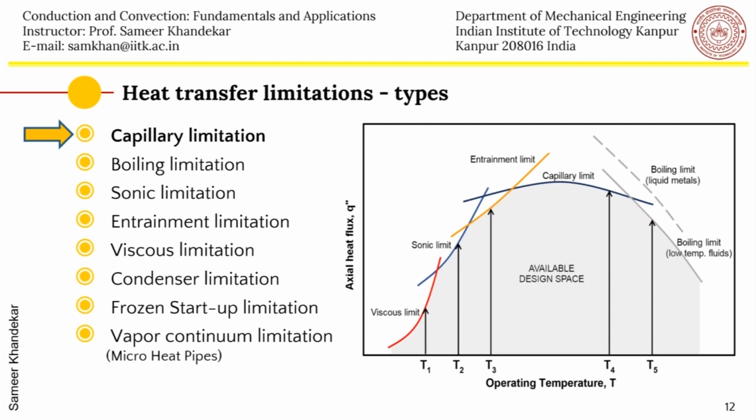As we will see, one can do a theoretical experiment in which you control the operating temperature of the heat pipe, which is usually the adiabatic temperature, by controlling the condenser cooling water temperature. That is the main way by which you can control the operating temperature. Approximately the R thermal will be known to you by a few experiments at that temperature, and then you can adjust the evaporator temperature accordingly.